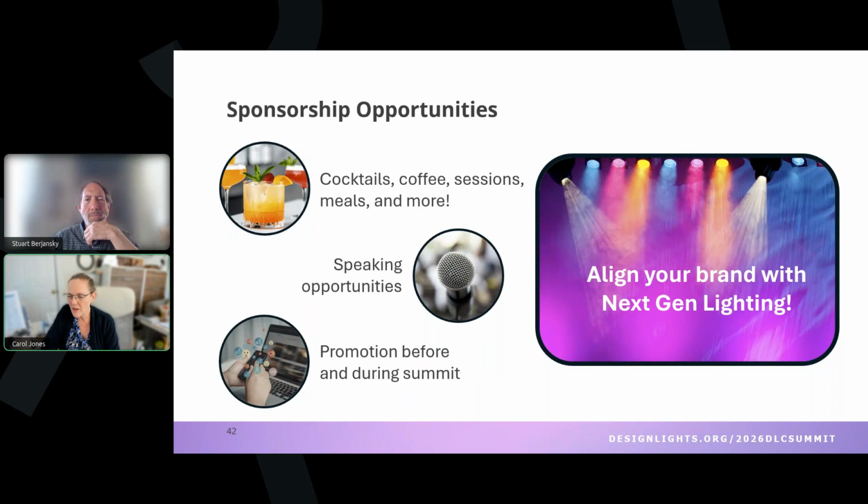I think I know what is being asked here. A subnet can have 64 control gear, like drivers, but also 64 devices. So think of it like 64 drivers and then that same number of switches or sensors. So can you expand beyond 64 and 64, meaning for the drivers and peripherals?